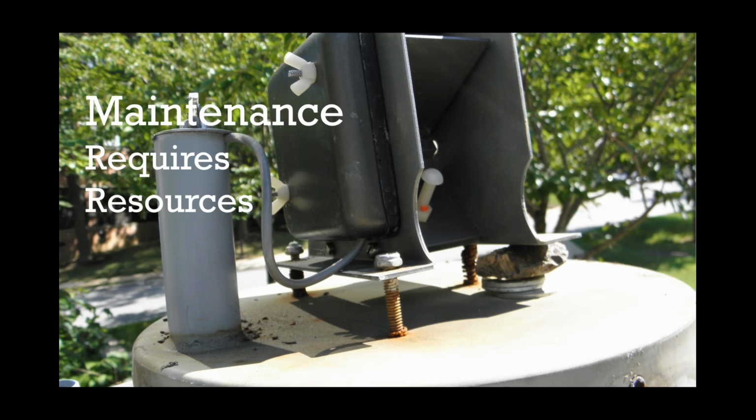Quality maintenance also requires resources, hopefully more than a rock and some flat washers to prop your bucket up to get it level. The springs have rusted out in this one. Unfortunately, out of a 14 gauge network, when we went in to do inspection on this one, we found 3 of them that had rocks, and one of them had taken a handful of rocks and duct tape and made it into a bigger ball to hold the rocks all together and propped up a bucket. Notice the back leg back there, it's already way down low. So there's no way this tipping bucket is going to report accurately.